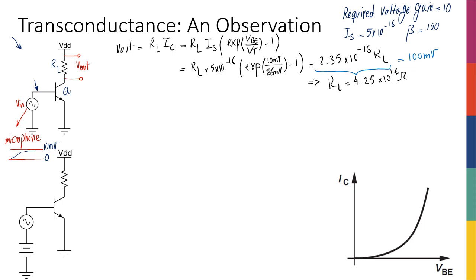Even if it is implemented, it's going to be gigantic. So imagine that you want all of these circuits, and this is a little amplifier, right? If you remember from lecture 1, I mentioned that in an integrated circuit, you might have, I don't know, billions of transistors. And if one single transistor, single resistor amplifier is going to have such a large resistor, if you implement it on chip, on silicon, it might actually take as much area on silicon as a billion transistors will take. So it's definitely not a good idea to do this. So this is something that we cannot have, right?